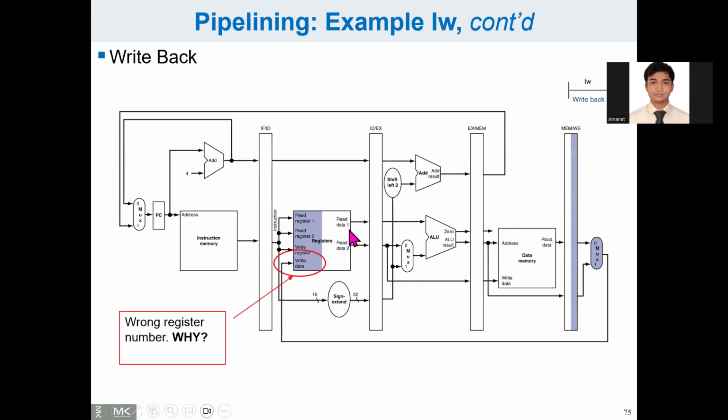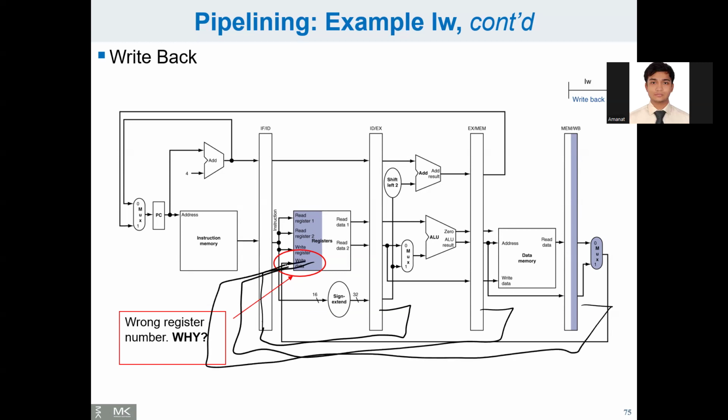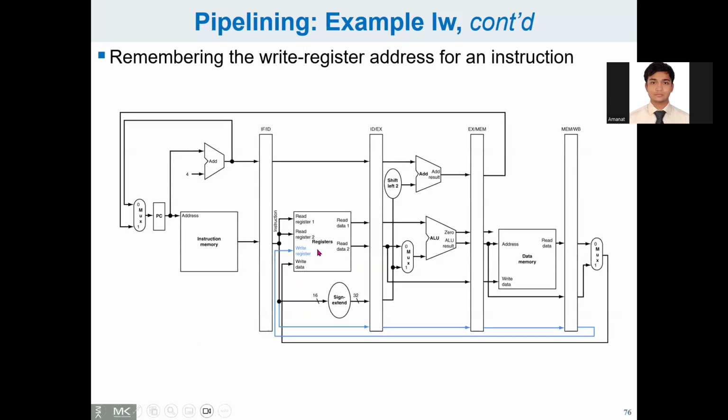So one thing is, when we have these saved values, this is wrong because we have to make decisions whether we are going to use these saved values or not, right? We have to use these saved values in some cases. So that's why this is wrong, and the correct solution is you sometimes need to make a decision whether you are using this value from this mux over here, or whether you are going to use the saved values.